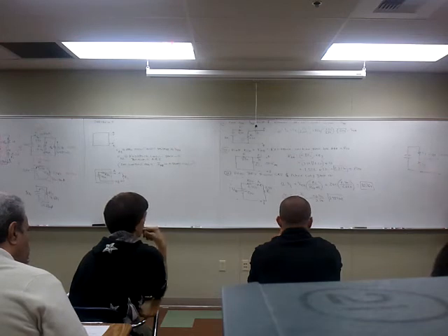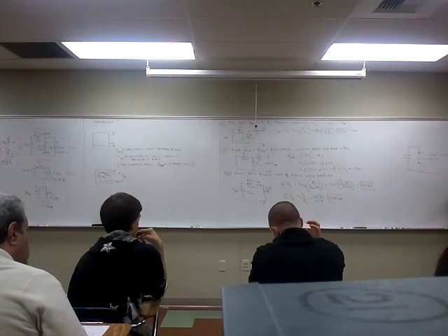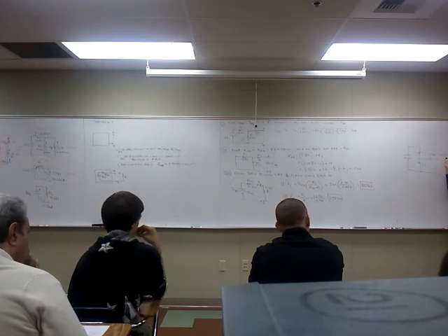That's very important in the world of electronics. When you have an open someplace, you tend to measure all the voltage. If you're working on a car and you measure 12 volts, people will sometimes interpret that as, well, power is applied. But couldn't that mean that you have power coming to this point, but the load is gone? It doesn't tell you anything about that load, does it? The load could be gone and it's just hanging out in free space. You got a wire hanging out there. So whatever you measure here has got to be the same as there, because there's no difference.